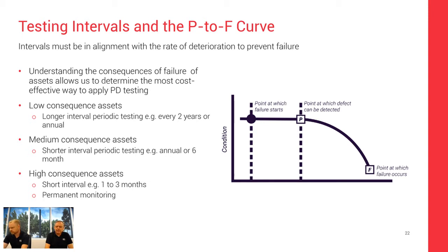One of the reasons for that is we're looking at very much void type problems. So compound insulated cable boxes, compound insulated chambers and oil filled switchgear. And if you're looking at a void degrading through bitumen and things like that, it's usually quite a long process before it goes into failure.